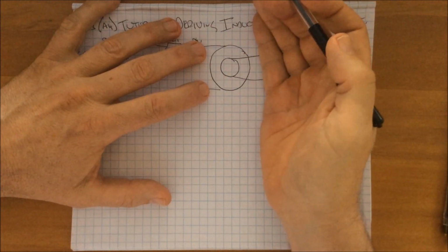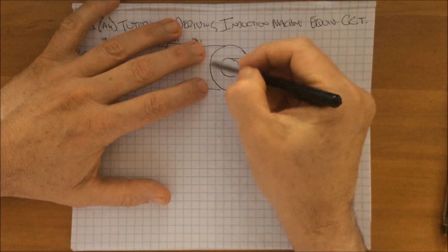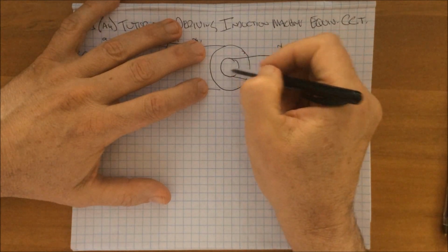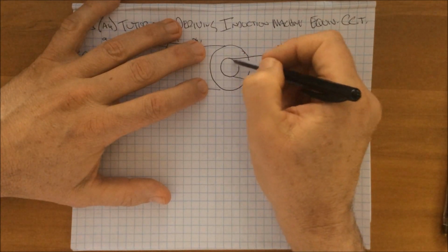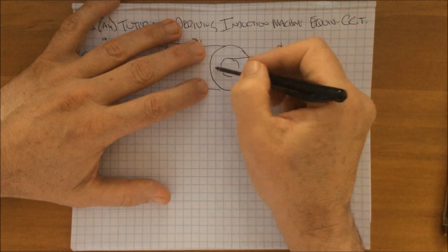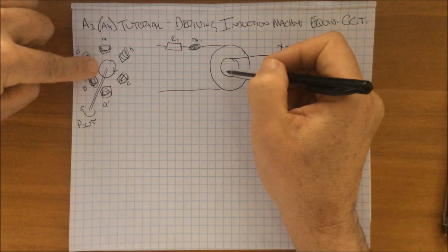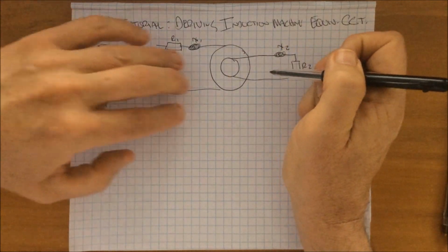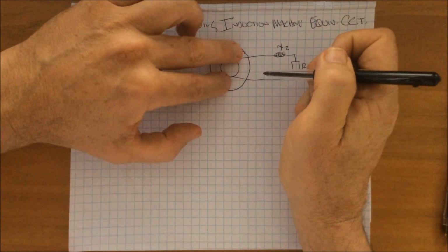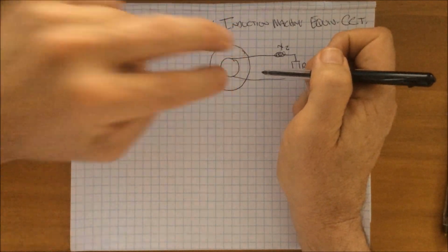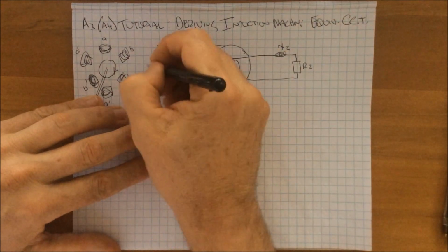Now, what you've got is a perfect hunk of wire, or sometimes it's coils, inside another coil of wire. This is what we've got over here, which sounds very much like a transformer. So what we can then do is replace this perfect set of wires with the transformer model. So this is our first stage.